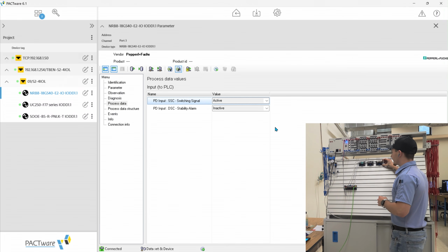There's also something to note. This is why it's important to look in your product description and or online and see what your sensor can actually do. This sensor has a certain range that it can max. It has a max distance for how far it can read a signal. And with these inductive type sensors, the range is actually pretty small. Only maybe 10 to 20 millimeters, maybe 20, it's probably less.